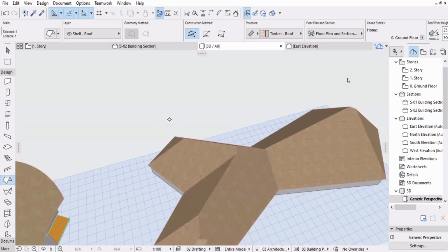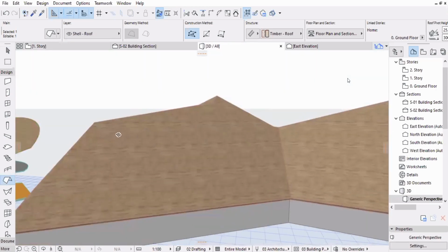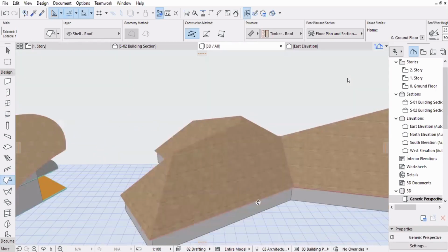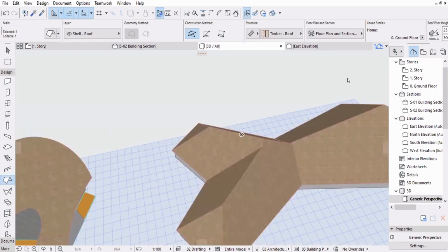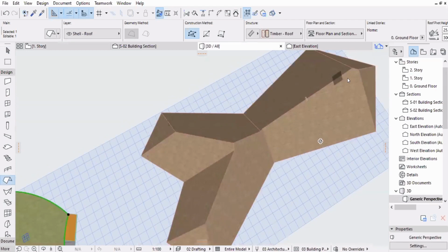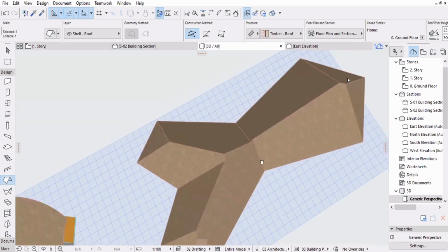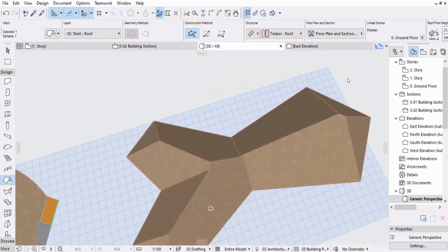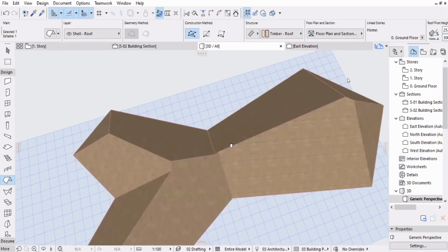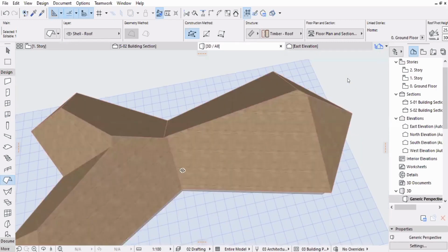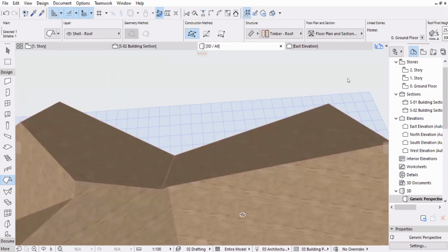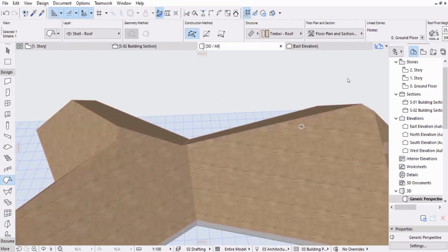The ridges are something it doesn't obey. It doesn't say the ridges have to be always horizontal, but it always obeys that the slopes have to be the same. And you'll get precise roof ridges and valleys and hipped ends and everything with equal slopes. But you might get things like this, which is okay because the span is slightly more than this. It has gone a little higher. Okay, and here there is a little bit of a problem because again, I guess some spans are higher on this side than this. But it does the job.